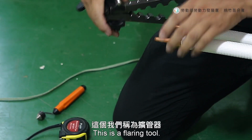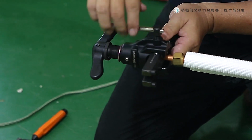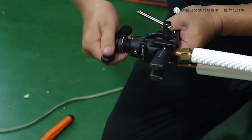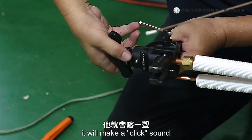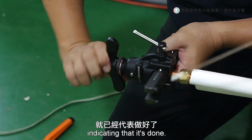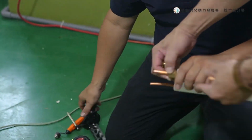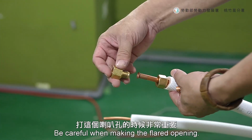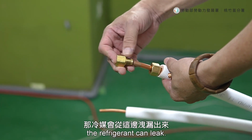This is a flaring tool. When this flaring tool reaches the end, it will make a click sound, indicating that it's done. At this point, we should remove it. Be careful when making the flared opening. If it's not done properly, the refrigerant can leak.